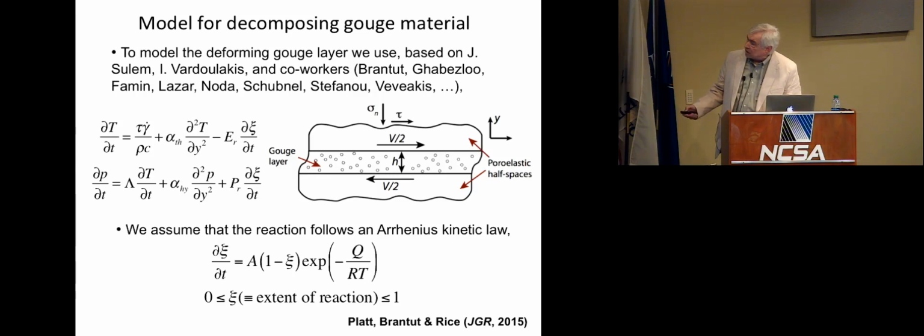So what changes in the description I gave you for thermal pressurization? Well, not much. You've got a lot of thermochemistry to deal with here, but in the end, it can all be summarized this way. Suppose C is the extent of reaction, and for simplicity, assume the reaction has Arrhenius temperature dependence, and we allow the possibility that you could completely deplete the reactants. That's this 1 minus C term here. Having the chemical reaction go on can all be described by a factor E, which describes how much a unit of the reaction has buffered what otherwise would have been a temperature rise from the stress working that's being done.